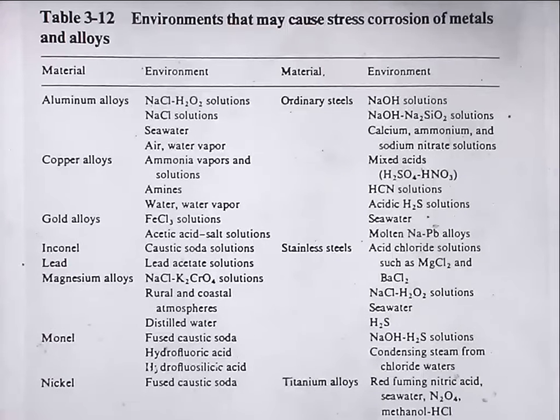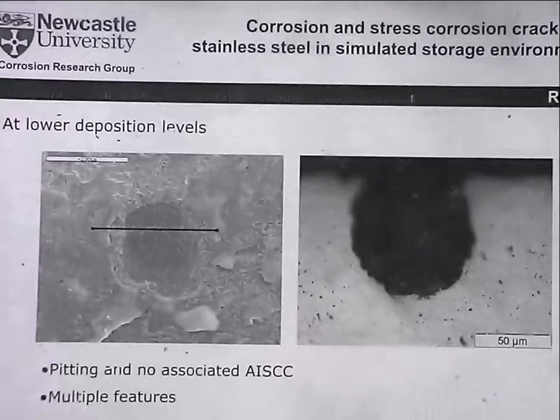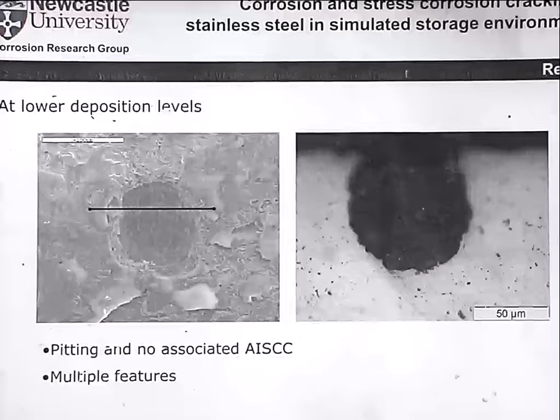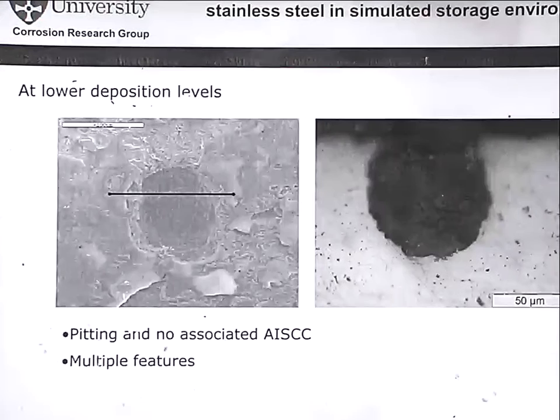There's a lot of discussion about how cracks start. This is an image, an aerial view, so to speak, looking down, and then a sectional view of a pit in some stainless steel in a particular environment. We needn't worry about that. There's a certain number of people who believe that you've got to have pits before you can have cracks. There are other people who say, no, you can actually have either. Sometimes you get cracks without any pitting, sometimes you get pits without any cracks.